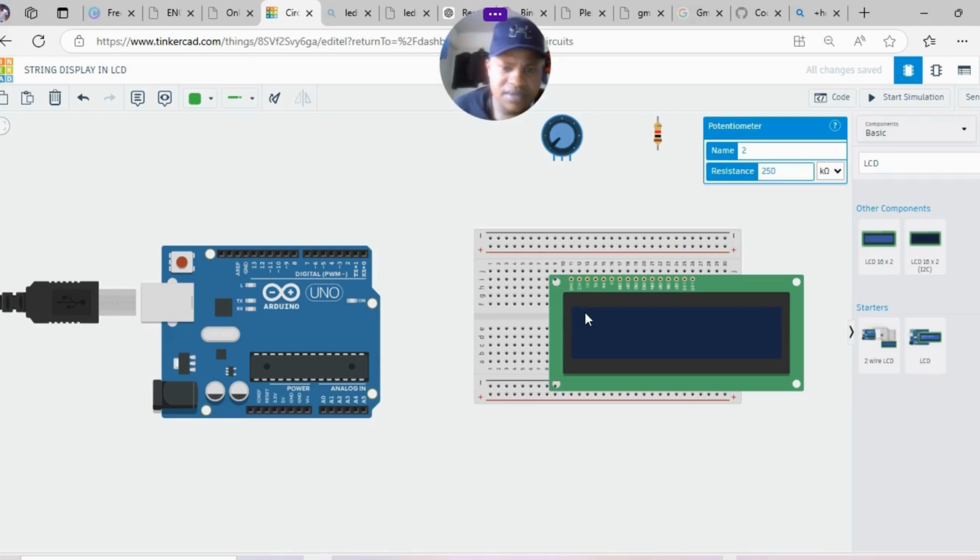And I'm sure maybe some are not conversant with these two modes. If we talk of the data mode, we simply mean that if we have configured our LCD to be under data mode, anything that comes to the LCD will be interpreted as a data character, and therefore it will display it.